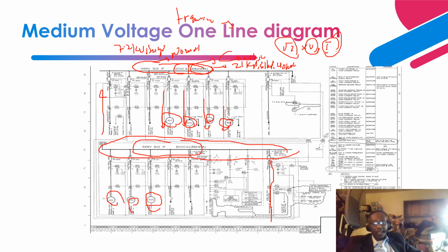And the incomer that is coming here to power this bus is also coming from a dedicated source, different from the other bus. The goal is to create redundancy, so that if you should lose a feed to this bus, you'll be able to trip this bus and close the tiebreaker to keep your loads